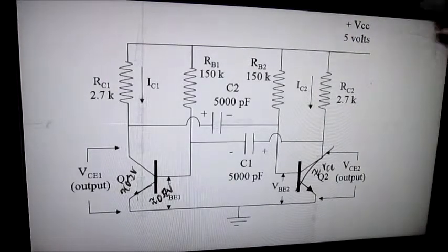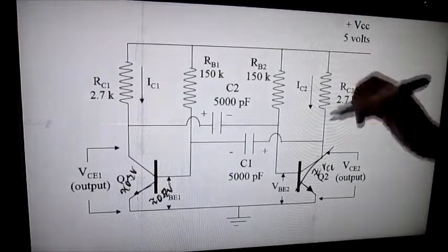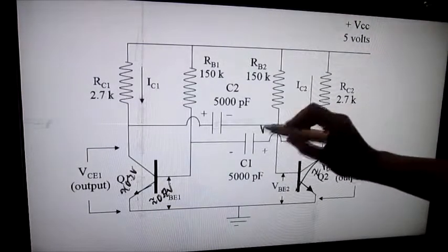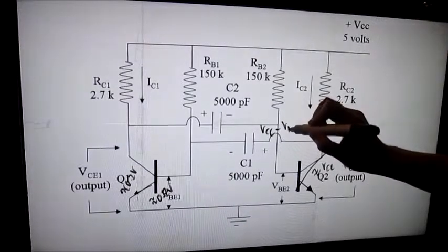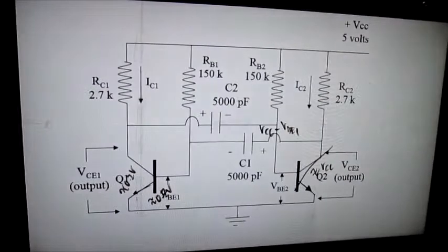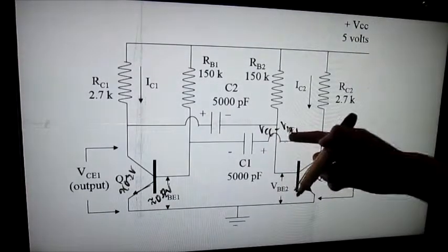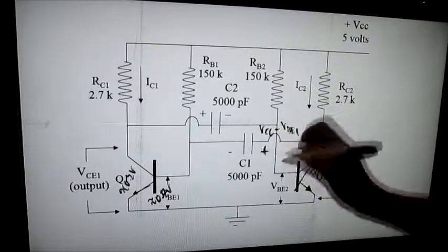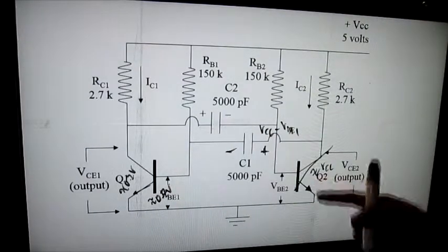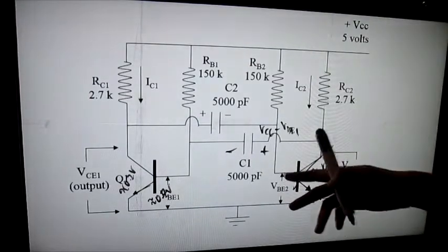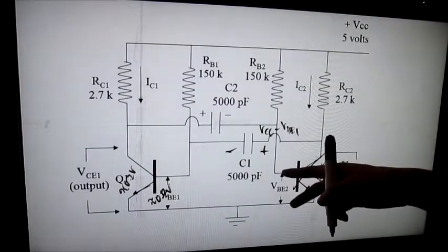which means that upon power up of the circuit, C1 is charged to VCC minus VBE1. Now, when capacitor C1 is charged to around VCC minus VBE1, positive on the right side and negative on the left, VBE2 rises from below ground potential to about 0.7.